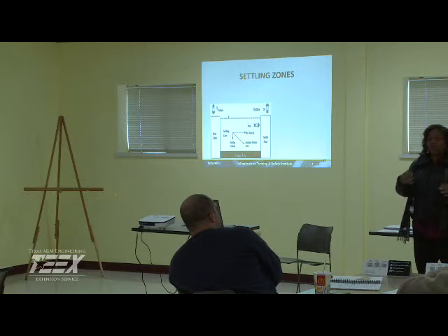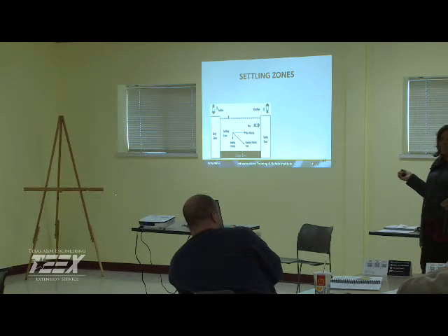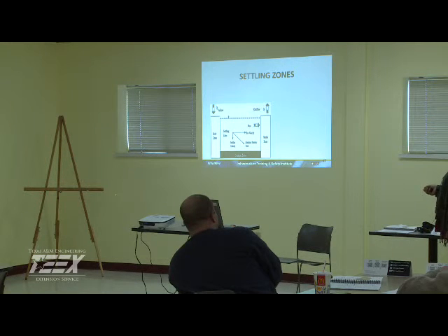Yes, you have to make sure you have a routine schedule to remove the sludge from the bottom of the sedimentation basin, because it can lead to taste and odor issues, as well as affect the quality of the water.